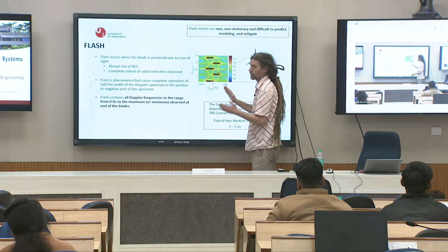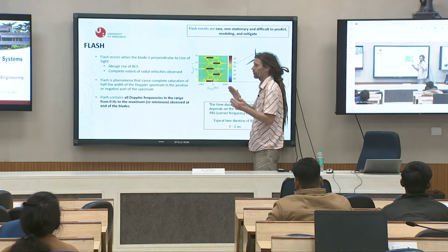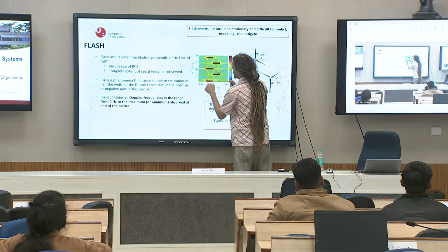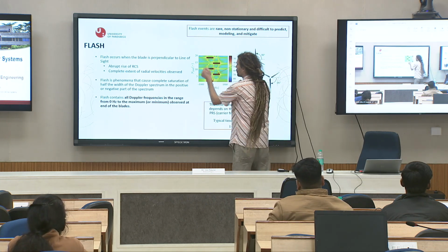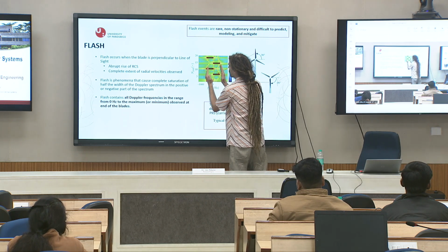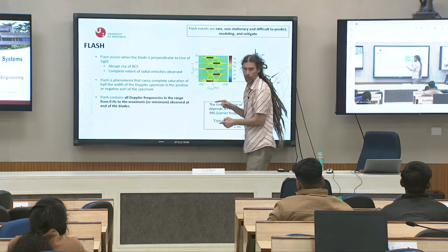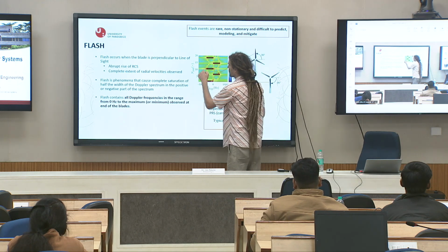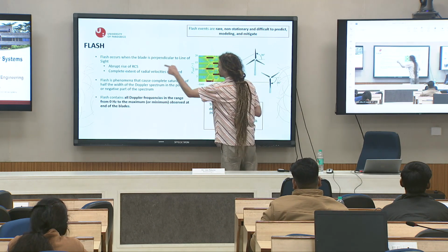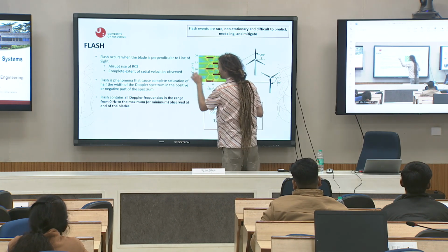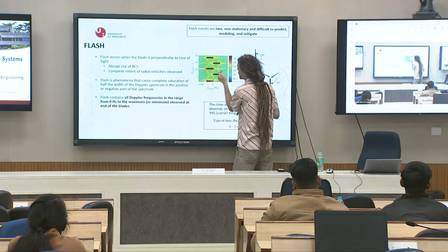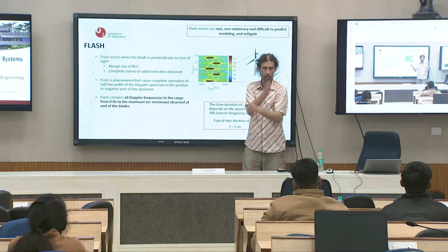With higher rotation frequency, these sine wave amplitudes get higher, higher, higher, and when I reach the maximum, it does not continue like this, but this copy will be aliased to this one, because it is aliasing.